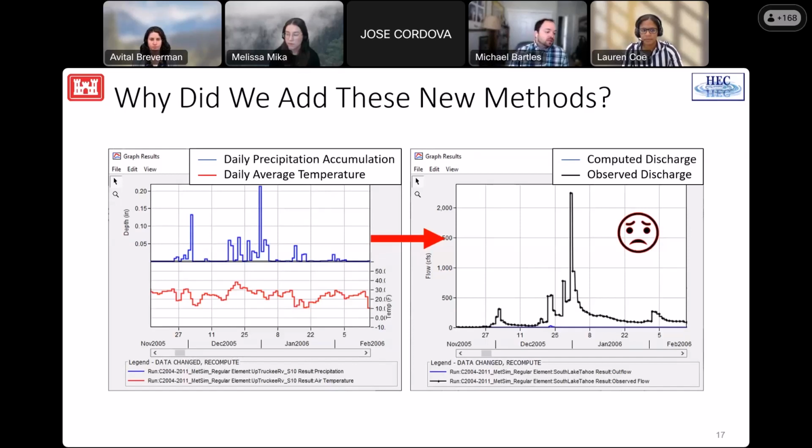If you've ever tried to simulate the 1927 flood along the Mississippi River, the March 1936 flood in the Northeast, or the January 1964 flood along the West Coast, you're likely not finding gridded boundary condition information for that, right? You want to use grids. Gauges are hard to use because it's hard to go from point to space, right? When we do have these boundary conditions, they're typically in a daily time step as well, which also limits their applicability to smaller modeling domains. If you've ever tried to use daily boundary conditions over a modeling domain of like 50 square miles, it usually doesn't work too well.